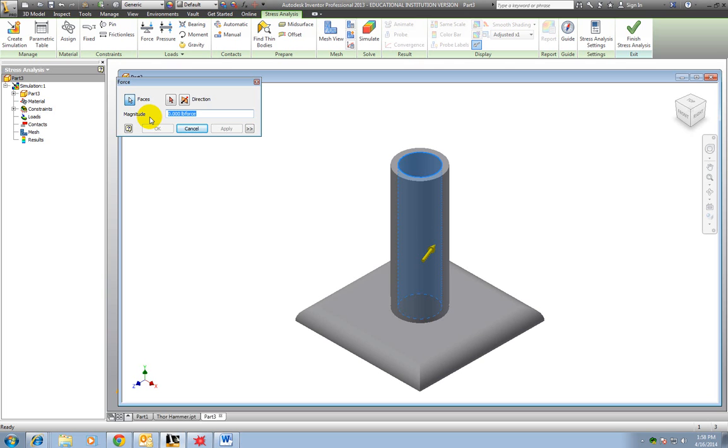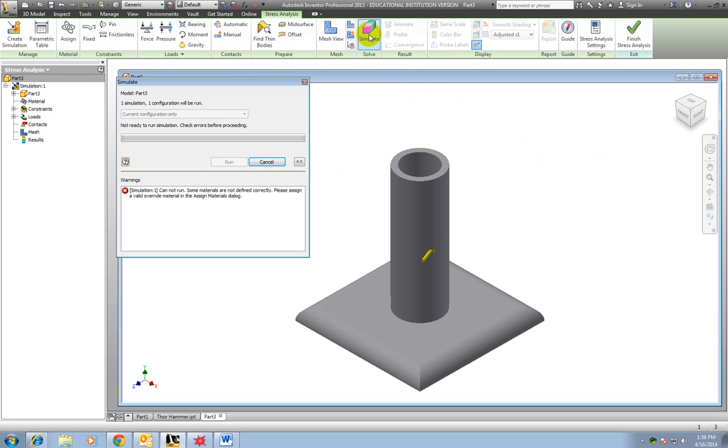So this one is a 24-inch, because remember I had made mine larger, so maybe for a flag I'm just going to guess and say 20 pounds. That might be a little bit overinflated, but I'm just going to throw 20 on there. Okay, and I'm going to apply that. Now I'm ready to do this simulation. There are so many other things you can do, but I'm just showing you a basic one that you need to know for this class. All right, so I click Simulate.